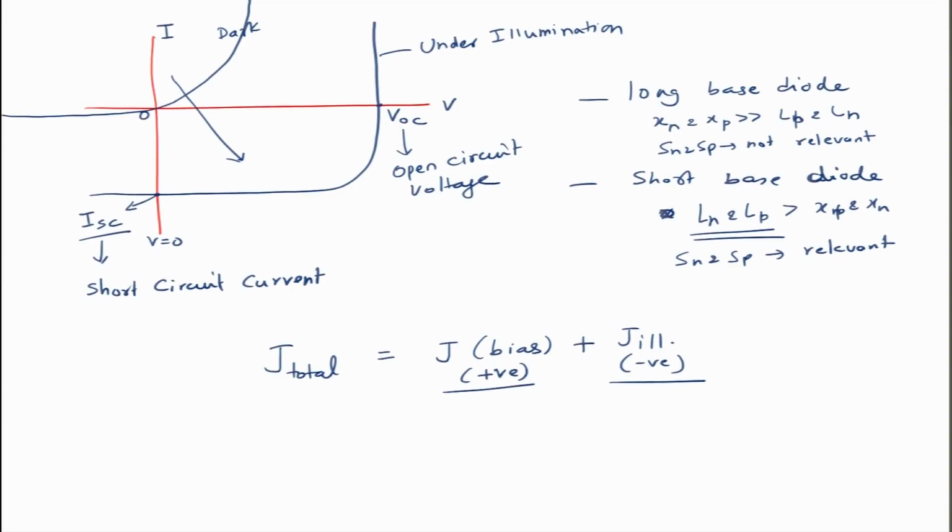And we also looked at the effect of various parameters on the quantum efficiency. We looked at the quantum efficiency showing a behavior like this. So, perfect quantum efficiency would be something like that. Okay. So, this is quantum efficiency as a function of wavelength. Whenever the quantum efficiency reduces on the lower wavelength side, it means the top of the solar cell is playing an important role, so this would be the top part contribution,